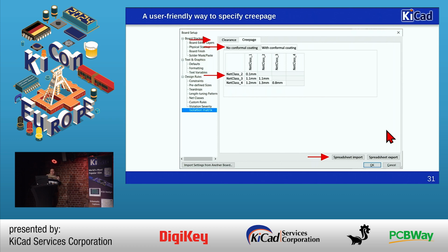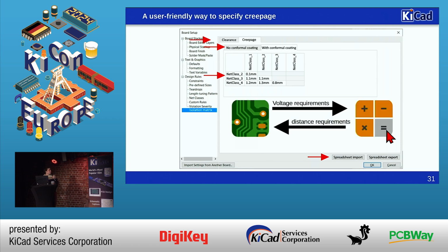One thing that I think about is that we want to withstand voltages. Distance is only the means of preventing arcs due to voltages. And we have the calculations from volt to distance. So maybe what we could do is, in the PCB new, set the voltage requirements as an alternative way to do things, and then ask the PCB calculator what the distance is, and then we get that automatically as a conversion.